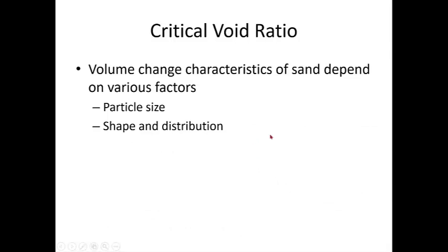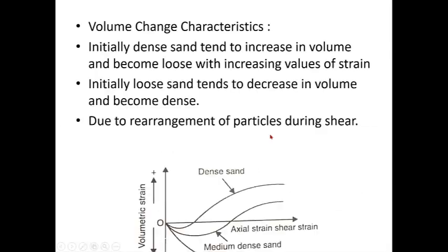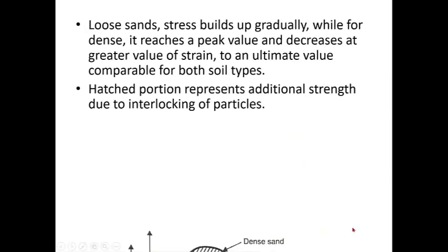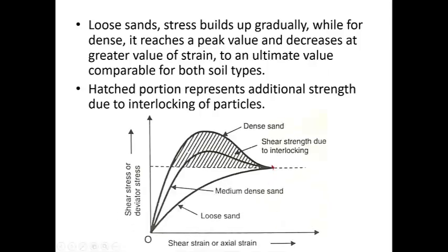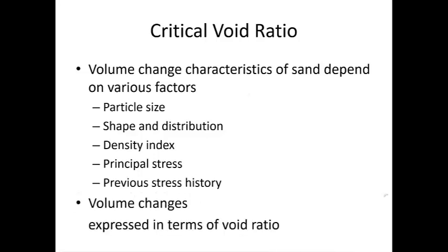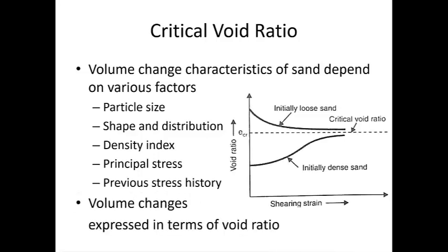In the stress strain behavior also we saw something like that. In all graphs we saw something like that. After this, it's going to be constant. After this, it's going to be constant. Again, after this, it's going to be constant. Your shear strength is also going to be constant. So after it has attained its critical state, this volume change, your shear strength, all of these are going to be constant.